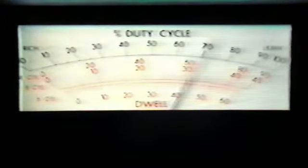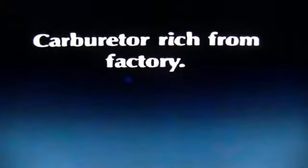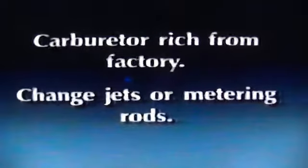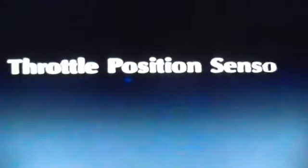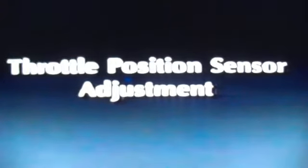If the 1/2 turn of the lean stop screw wasn't enough to achieve 30 degrees dwell at 2,500 RPM, this would indicate the carb is calibrated too rich from the factory. As a result, it would be necessary to change jets or metering rods in order to maintain 30 degrees dwell at 2,500 RPM and stay within a half turn of our bench setting on the lean stop. After the 30 degrees dwell has been achieved, it's time to move on to the final TPS adjustment.